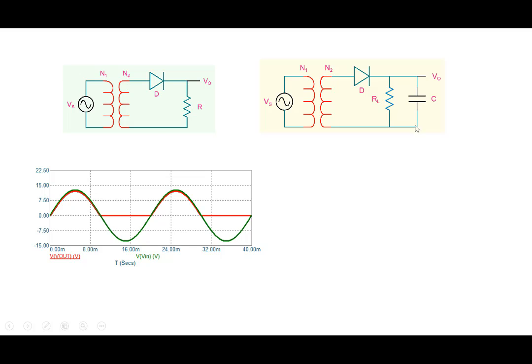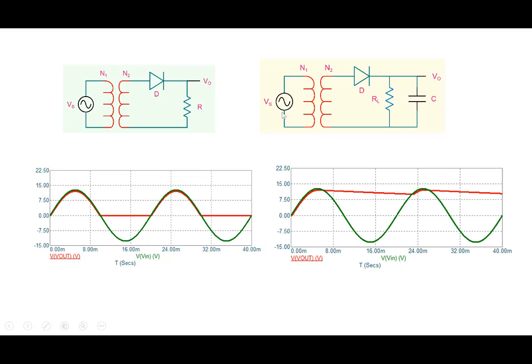capacitor. And so the idea is that if we choose the capacitor to be large enough, all the frequency components will get shorted. And for DC, the capacitor is an open circuit, and therefore the DC voltage will remain, and all the frequency components will get shorted. And so let's see what happens here. So we connect a capacitor. This is in red is what is shown over here.